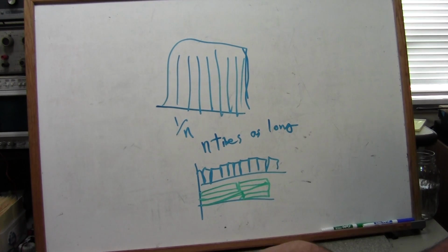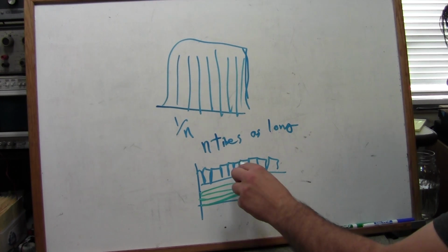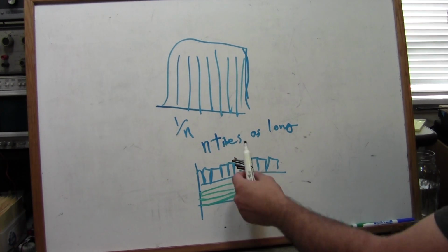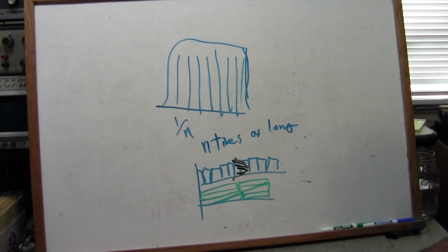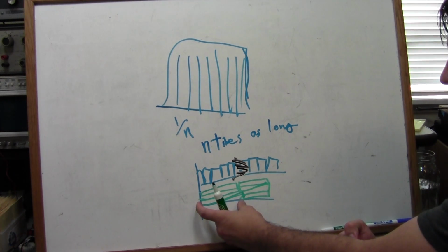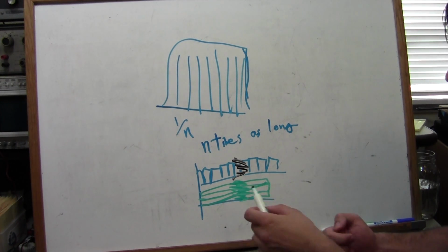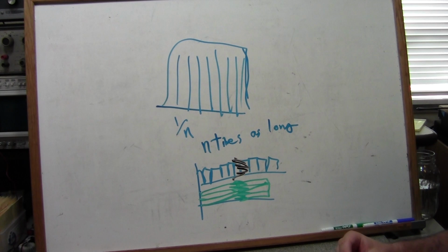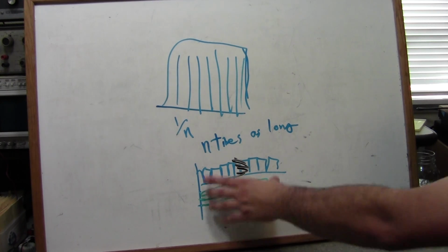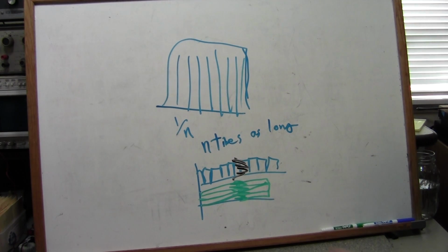When you have lots of very short symbols like this, and the transition between them gets a little messed up, you can lose complete symbols. By having many more longer symbols, the inter-symbol interference in the middle here becomes a negligible fraction of your symbol rate and allows OFDM to be more robust to this phase shift or phase noise or frequency error interference caused by each of these, which causes this blurring.